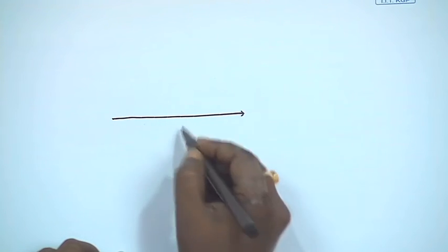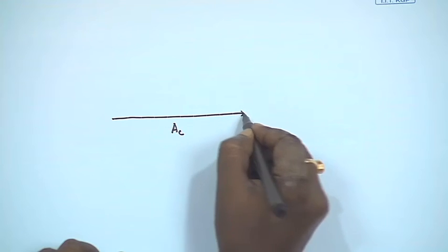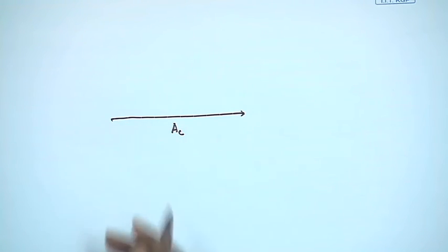If you remember the phasor diagram we have drawn, this was AC, which is the signal, and in the phasor the phase is the reference. Because FM has AC cos omega c t plus kf integration m alpha d alpha, that entire thing is the reference.